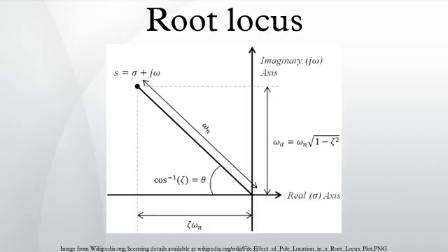Compute breakaway break-in points. The breakaway points are located at the roots of the following equation. Once you solve for z, the real roots give you the breakaway re-entry points. Complex roots correspond to a lack of breakaway re-entry.